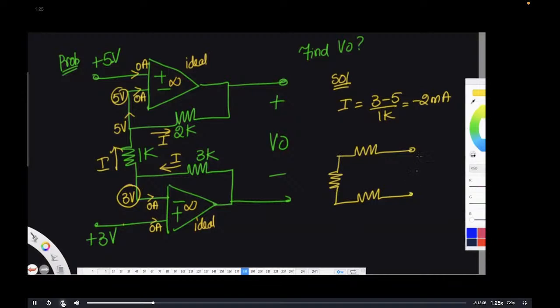See, this is why op amps are so easy, because once you apply virtual ground, it's a problem of resistors. It is a simple problem of resistors, right? You can just remove the op amp from there, keep the resistors, and then calculate. Because once you apply virtual short, the voltage at the non-inverting input is the voltage at the inverting input. You don't need an op amp anymore to calculate. So you can tell me what is the KVL here.